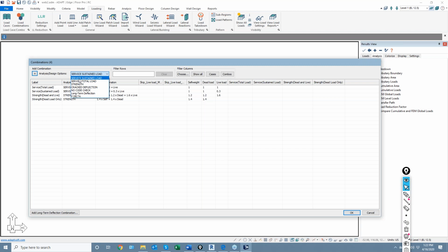When we talk about reinforcement for these two combination types, the program is really calculating minimum reinforcement for whatever criteria you have set for your design strip. So if you've set a two-way criteria for a design strip and there's no post-tensioning in the model, it becomes two-way RC. And therefore, for two-way RC slabs, we check minimum temperature and shrinkage reinforcement.